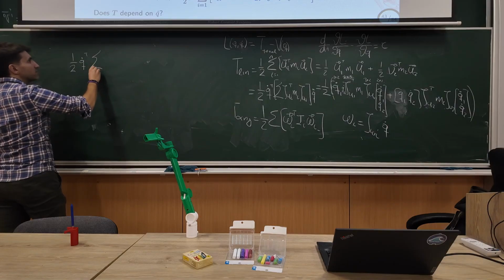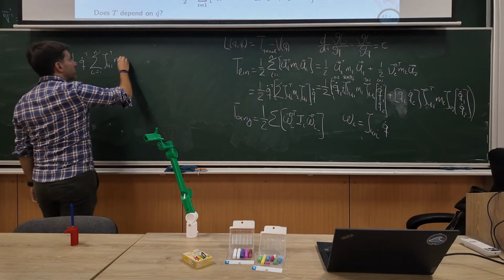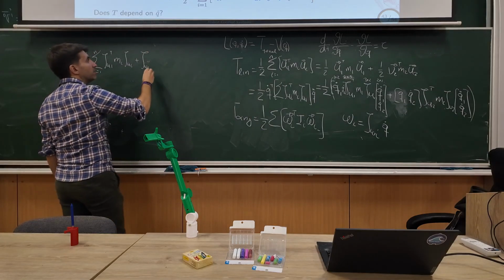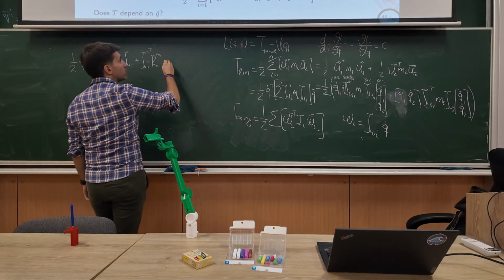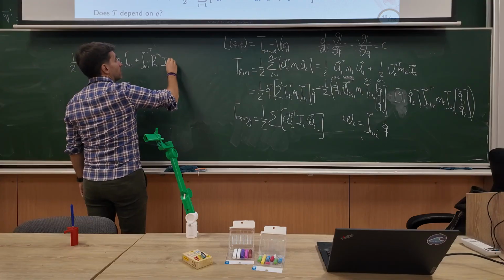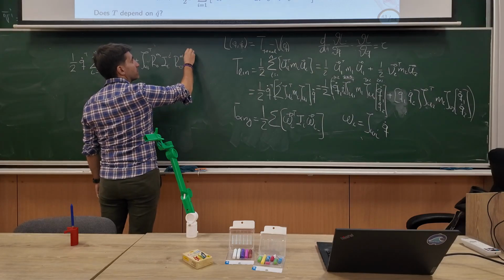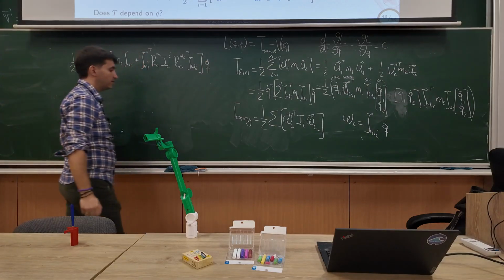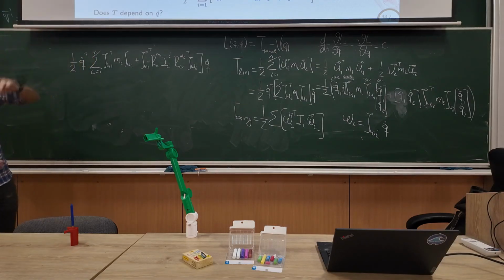It's not dimension analysis, that's not the right term, but anyway. And Jacobian v_i transposed, m_i, Jacobian v_i, plus Jacobian omega_i transposed, orientation matrix, moment of inertia with respect to its own frame, orientation matrix transposed, J omega_i, Q dot. This is for n degrees of freedom, n joint robot, right? We saw the example with 2, but as I say, this is the general form for any robot.